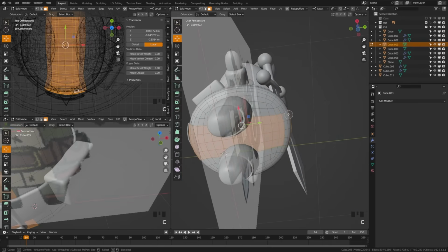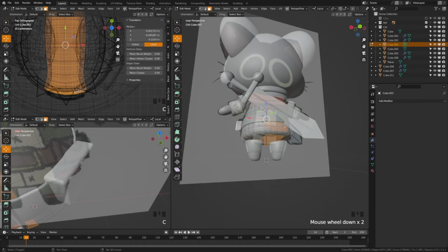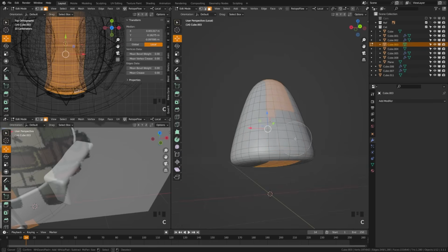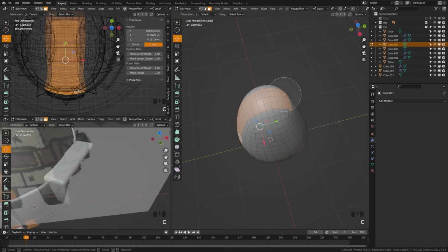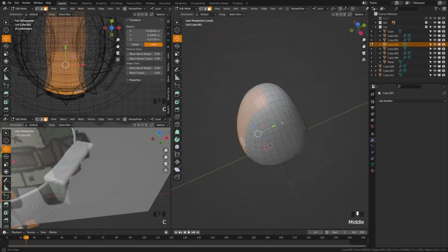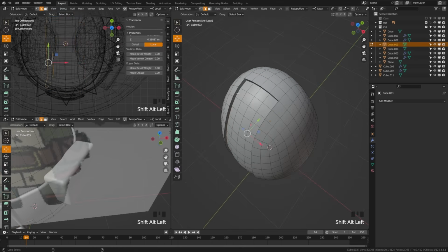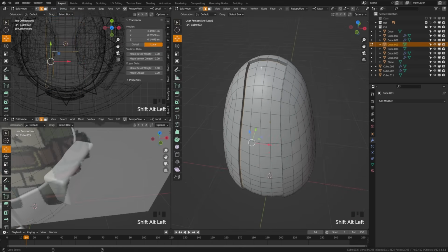So I'm going to press C to switch to the selection tool. And by dragging with the middle mouse button, I can deselect faces. To make sure you see things easier, tap /, and that'll make it so that you isolate the selected object. And then when you're done, tap / again, and it'll go out. Once you've got your selection, hit I, Control, and drag in a bit. And you can see there how we get that inset.